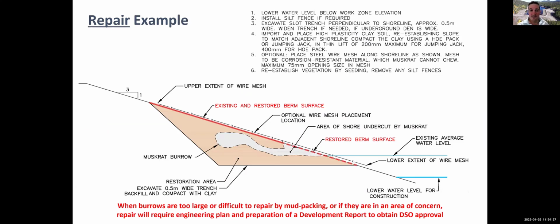The toe areas, Dwayne showed the zone 1, zone, I can't remember, it was 4, and I think that came from some FERC design guidelines. But these are areas of critical concern that you really want to look for, because they can really impact internal erosion. And internal erosion is roughly half of all dam failures. This is where the rodents are really problematic, and the root bulb, if your tree gets torn out.